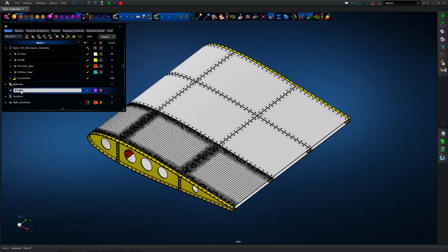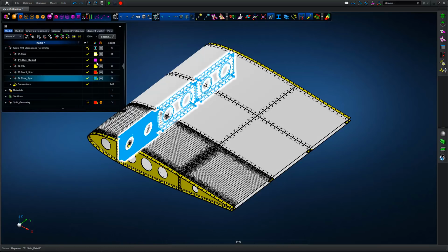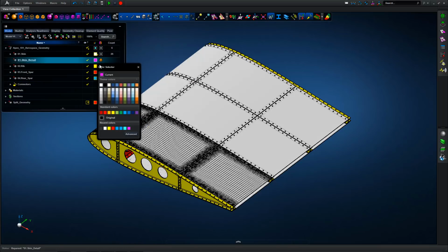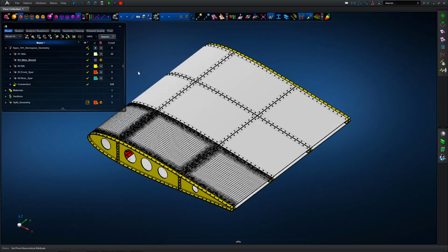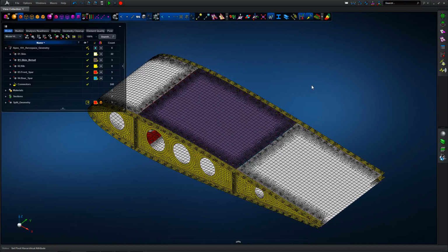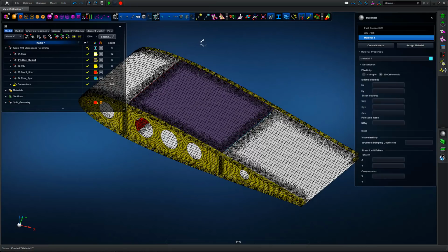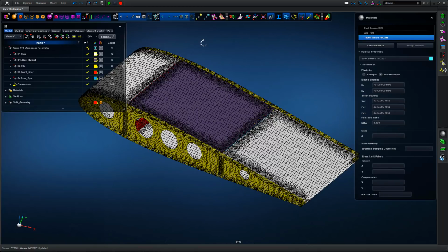So we're good to go in terms of the model connectivity and mesh definition and properties for the bulk of the region. We're now going to look at composite modeling and analysis, or composite part definition. So to simplify the model browser, we've created a new part, or a new subassembly called skin detail. And for the large rectangular skin, we're going to move the surface and meshed entities into that subassembly. That will give us benefits in terms of post-processing and some model manipulation downstream.